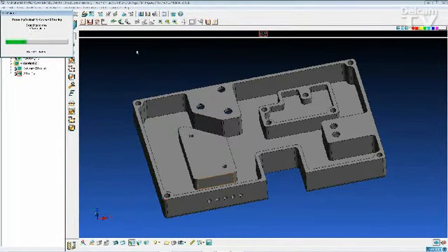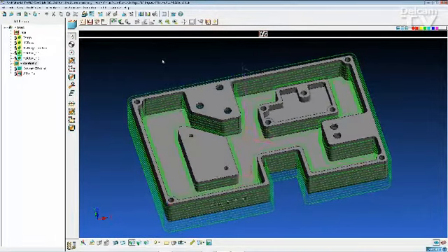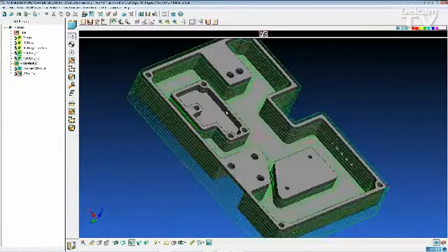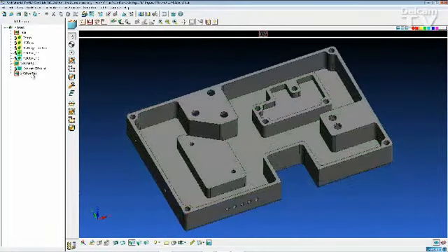In between each level, it will actually be spiraling down, so the level is continuously lowering itself in Z throughout the cut. So it engages at the top of the part, and as it's cutting around the next Y, it'll be plunging slowly down in Z until it gets to the bottom and leads out.